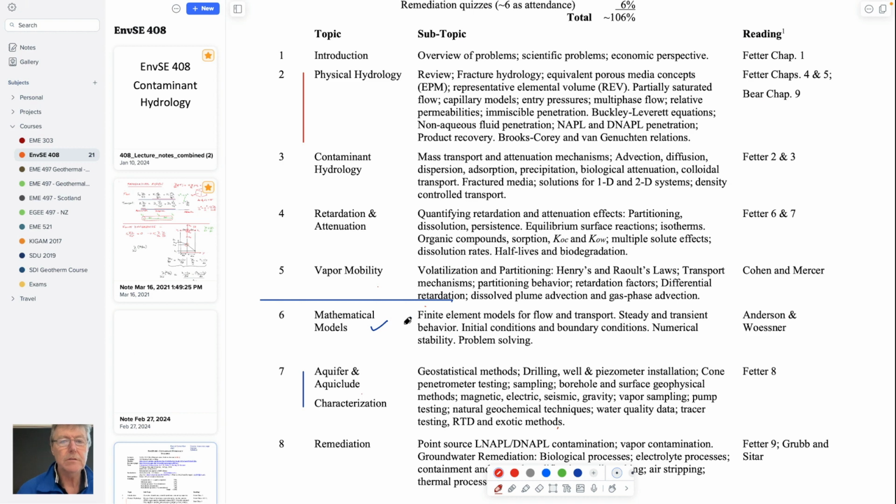That source is important because water flowing through it, even though these compounds are only very mildly soluble, they do dissolve, and they are a problem at really super low concentrations. And so their transport from that zone by advection and diffusion is important, and we talked about some models or methods to be able to understand both the physical processes, diffusion and mechanical dispersion, and advective transport in moving them from upstream to downstream.